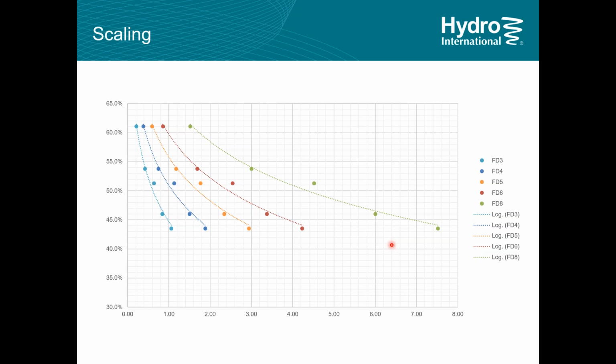The most common, and this is becoming very common now, is what we call surface area scaling, where you just keep the load rate constant. So if I test my 4-foot unit at 35 gallons per minute per square foot, I then assume that my 6-foot unit is going to perform the same at 35 gallons per square foot. So I can increase the flow rate by the increase in square foot.